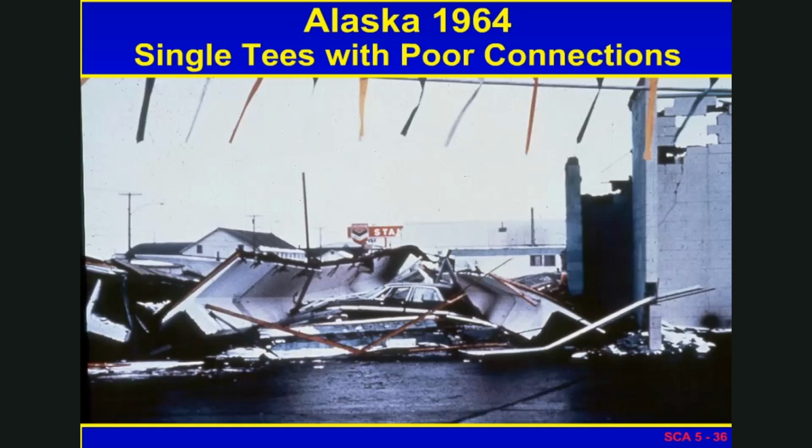This is one of the collapses from the Alaskan earthquake, where the large T roof collapsed, and you can see that if you're in the wrong place in this particular one, the survivability is low, although there were survivors in this particular structure. You can see how the large T's form some voids and where the victims would be. Since this is only a roof, all the victims would be beneath the collapse.